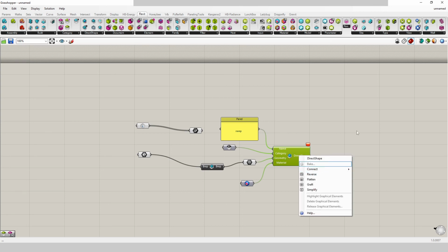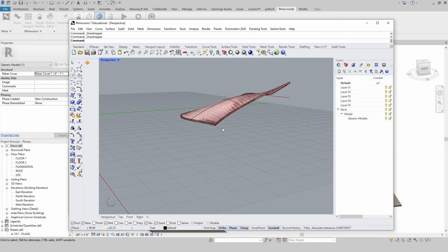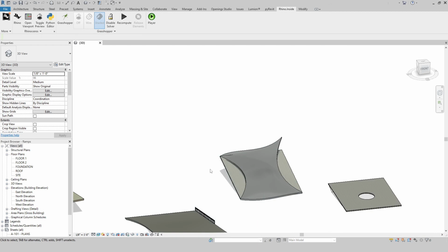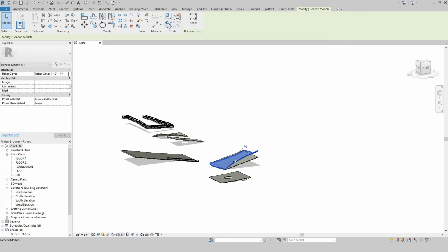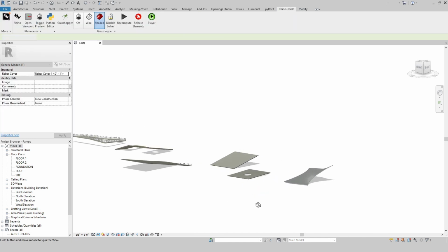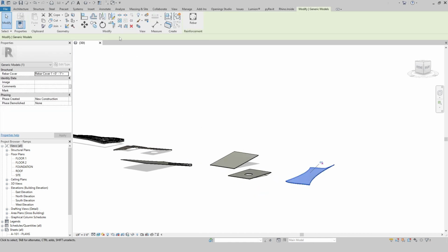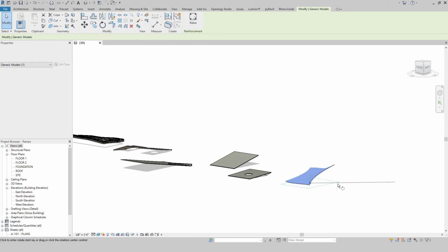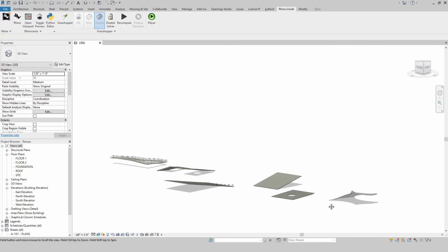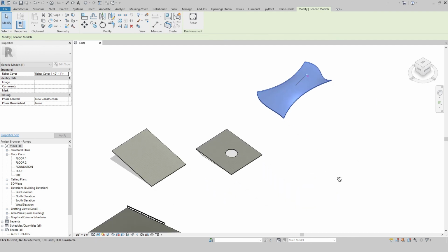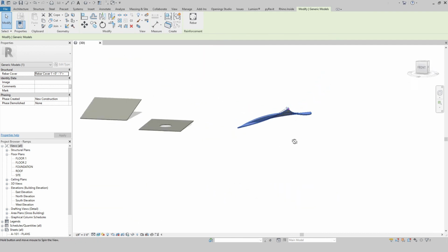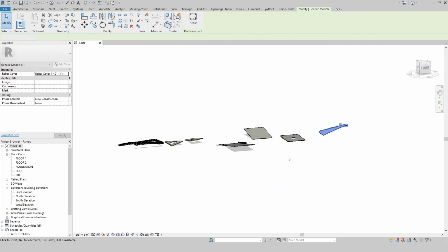And if I can't bake this, anyways, that's one approach that you could look into to get more of your material settings correct. So the point of unpinning this is that you could move it around, right? You could select it. There's certain things you can't really do to it, like scale. It'd be really nice if that was incorporated to be able to manipulate it a little bit more, right? But you can rotate it, you can move it. If you need to change the scale, you gotta do that in Rhino or in Grasshopper. But it's a great way to make some pretty crazy geometry as well.